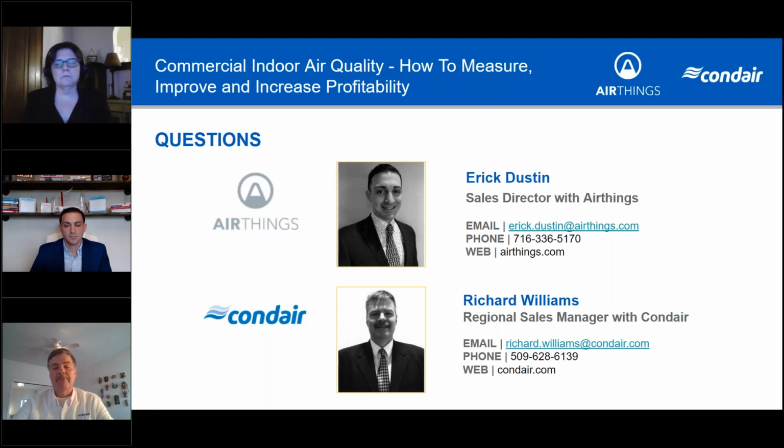And then that information is continuously sent back to the PLC controller. And then when there is a call for demand, because say the humidification level has dropped or is starting to drop, then the system automatically will spray water or atomize water into the zone where the call for demand is coming from. And the system can be zoned from as simple as a single zone to systems that we've done that have been 40 zones. So again, it's a very flexible, very customizable system that can be set up for multiple zones.